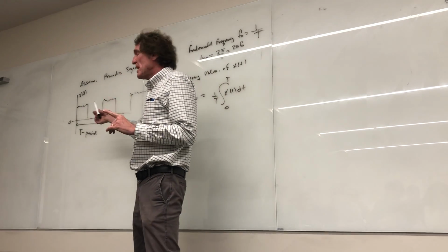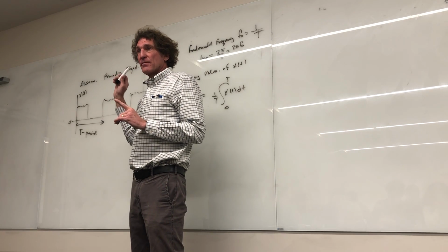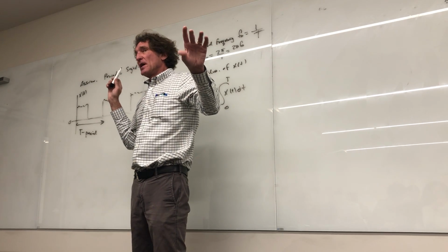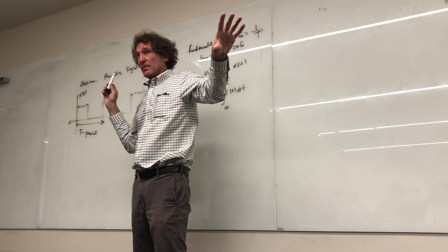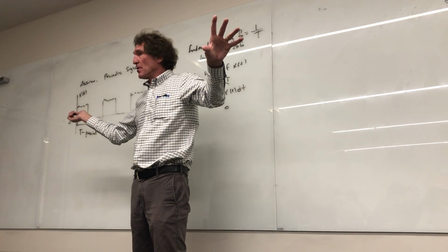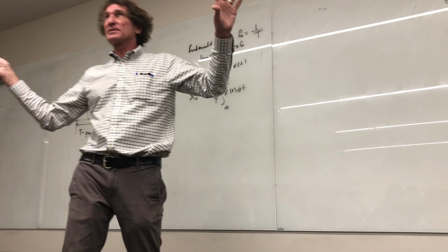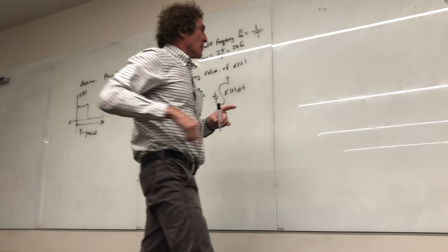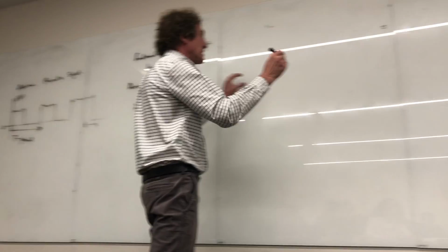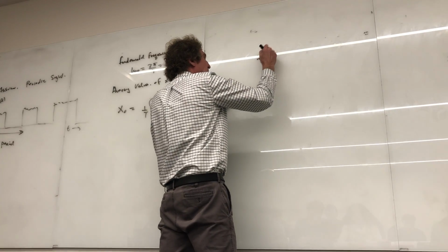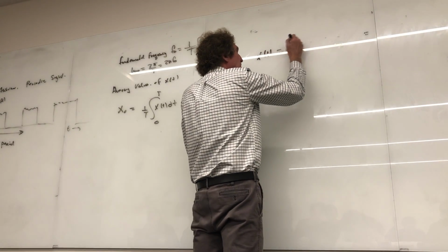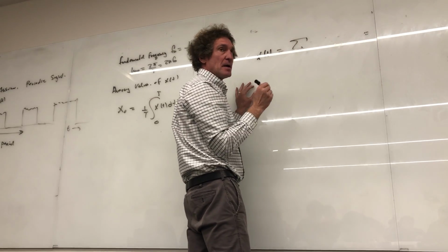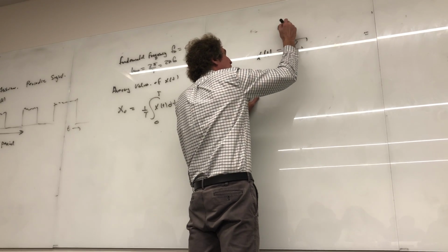This is a very powerful technique, because we're going to do this. We're going to take waveforms that are periodic waveforms that are fed into circuits, and we'll be able to get the output for a periodic, non-sinusoidally varying, non-sine or cosine varying waveform. And this is so important with circuitry. So what do we do to do this? Well, we say that x of t, if it is periodic, can be rendered as some infinite series. Write this down. This is going to be the exponential Fourier series.